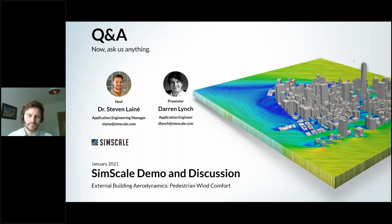So we don't have to have a super high resolution mesh near to the wall itself, but we can actually get away with a coarser one. But then this transitions somewhere in the buffer layer to the large eddy simulation, which is much better for predicting separated flows, which traditionally is what we're dealing with for external building aerodynamics.